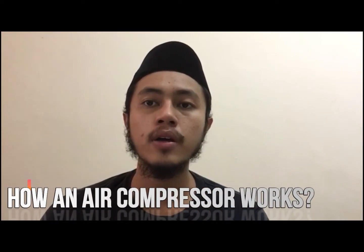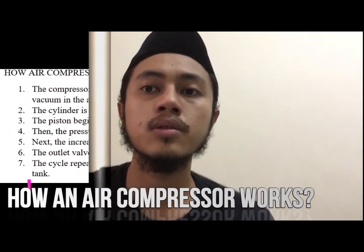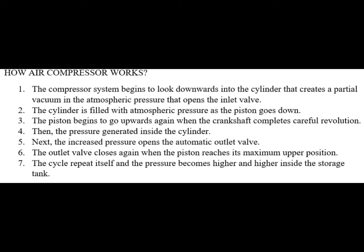So, how does an air compressor work? First step, the compressor piston begins to move downwards in the cylinder, which creates a partial vacuum relative to the atmospheric pressure that opens the inlet valve. Second, the cylinder is filled with atmospheric air as the piston goes down. The piston begins to go upward again when the crankshaft completes a revolution.